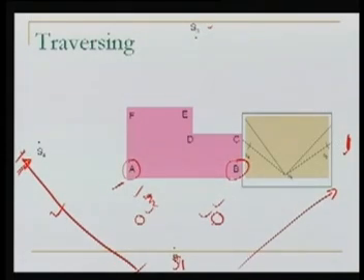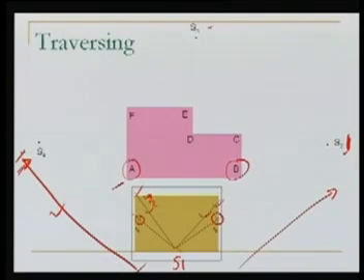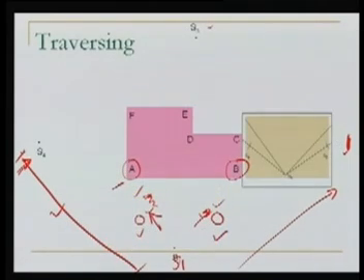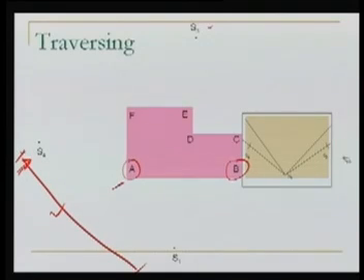So if I take the plane table to S2, you remember what was there in the plane table? Right at this moment in the plane table, we have S4 plotted, S2 plotted, and this resector and this resector, these are plotted. So when we carry the table to S2, we will have all these on our table.